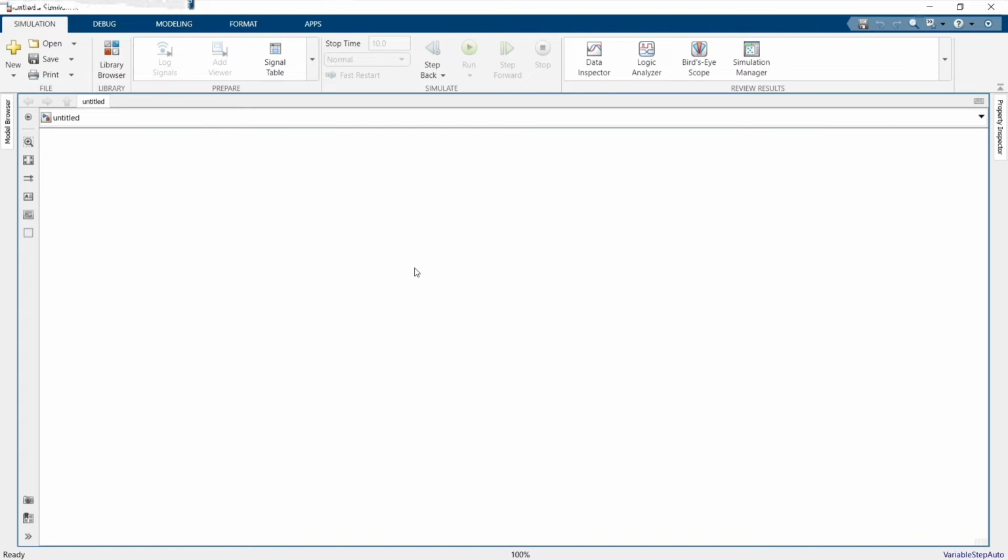So again, I'll just copy and paste this connection port, Ctrl R to rotate it. Then I will connect. Instead of in, I'll write out positive. Let me copy and paste it, and out negative. My boost converter is completed.